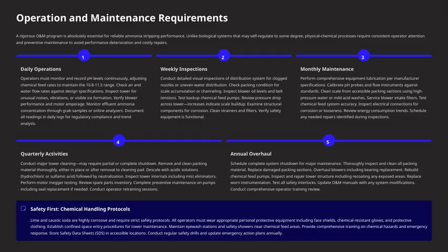Verify blower performance and motor amperage to ensure everything is operating smoothly. Monitoring the effluent ammonia concentration, either through grab samples or online analyzers, is essential. And of course, all these readings should be documented daily, not just for regulatory compliance, but also for tracking trends over time.